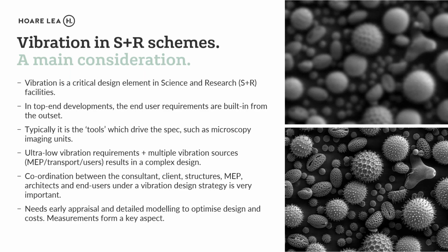And because of that, there's a high level of coordination that's required. So you first have to get an understanding from the client to see what actual vibration limits are specific to their facilities. And then how does that affect the structural design? How's that going to affect the building services design? How's it going to affect movement through the building? So you can see when you start to build in all these different parameters, vibration is very important.